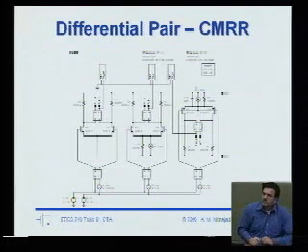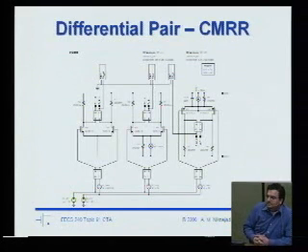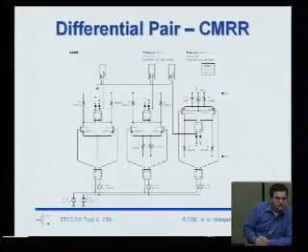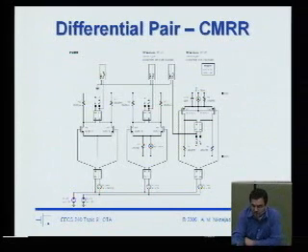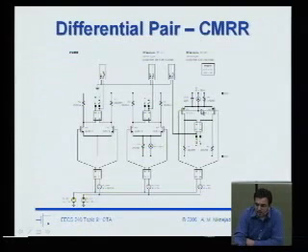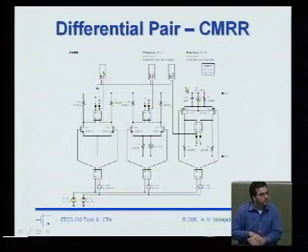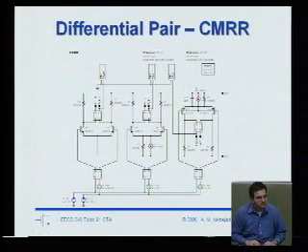Okay, there's capacitance between the well and the substrate. Very good, right? Because now I've tied my source to the body, and I see that full well capacitance. And that could actually be quite large. So that's why, in SPICE, if you don't tell it, SPICE knows nothing about the well. So you have to explicitly add a capacitor here to model that well capacitance. Okay, very good.